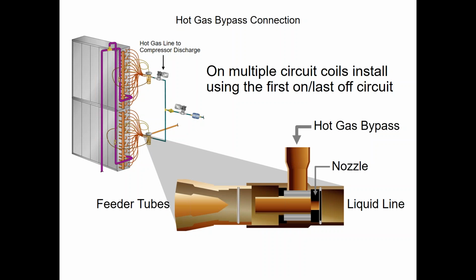But now we get into the screw compressors, and your screw compressors do not have oil sitting in the compressors. We have an oil separator, an oil vessel in the system that manages the oil that's pushed around by two things. One, an oil pump, just like in a car engine. And then two, the differential of suction and discharge pressure keep the oil in circulation on our screw compressor chillers.